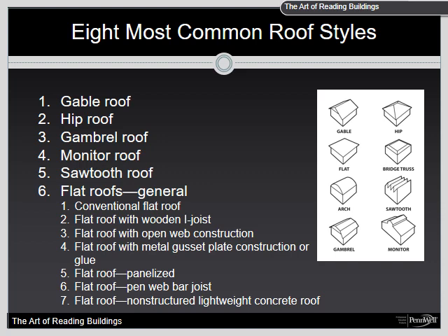The rafters are covered with a 1 by 6 inch sheeting of plywood or OSB, again with newer applications using composite roofing materials such as rock or other similar material. Older conventional flat roofs on masonry construction commonly used lets in the walls to support the rafters and joists. This is an old method, pre-World War II, that is no longer used. Newer buildings use a ledger board that is connected to the load-bearing walls.